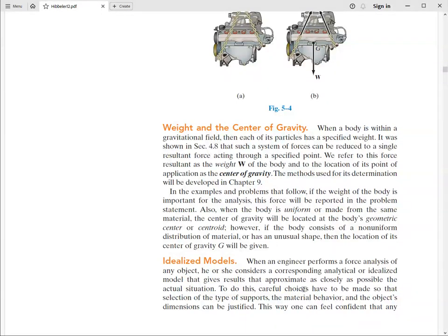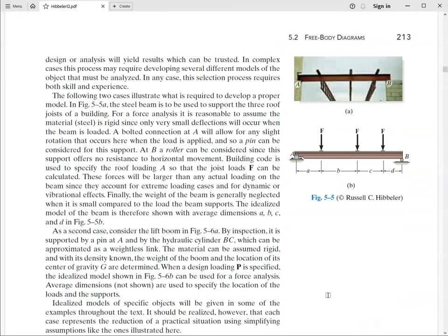And then we're dealing with idealizations. One, we assume rigid bodies are not deformable. Two, if they deform, they do so without any resistance. Cables and springs resist deflection, but we're assuming them to be massless. Likewise, ropes would be considered massless. And oftentimes we neglect the own weight when external loads are much bigger, as is the case here.